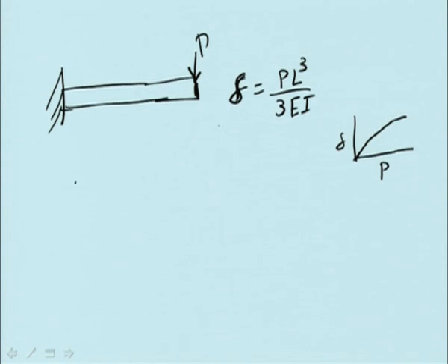You can do one simple experiment: take a beam and put it between two adjustable clamps, and clamp it properly with a screw. When the length is large and you displace it slightly, you can observe its natural vibrations. It will vibrate with a longer time period, that means less frequency.